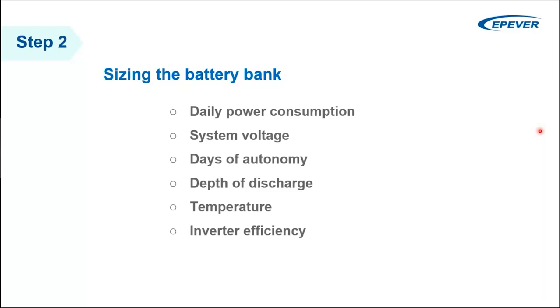Well, the battery is recognized by its voltage and capacity, measured in amp hours, and to provide the desired system voltage, one can wire the batteries in series and parallel. We will have another webinar in the near future about the wiring and configuration of the batteries. For this webinar, it's important to know that it's not good to parallel the batteries in a large number of strings, because a little voltage mismatch in strings will lead to a shorter lifespan of the batteries.